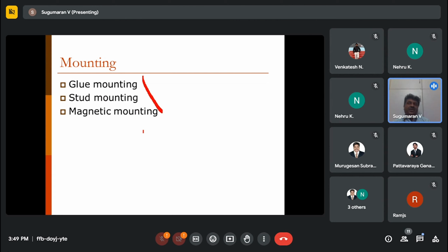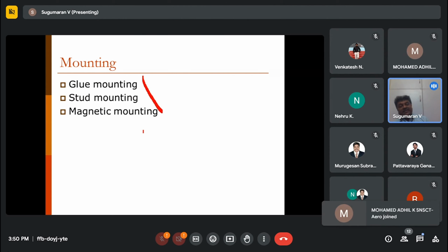Convert it into frequency, rotational frequency, and keep that, assuming that there is no fault. If there is a fault, then you should take the characteristic frequency equations of those faults, find out the characteristic fault frequencies, and calculate and keep those frequency components also.